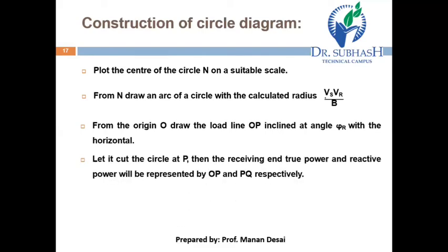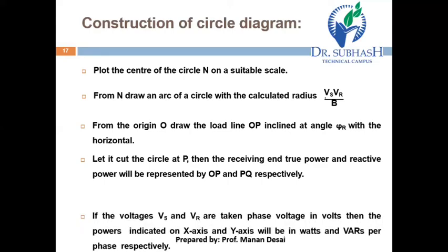Let it cut the circle at P. Then receiving end power and reactive power will be represented by OP and PQ respectively.